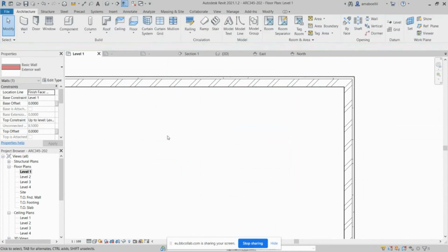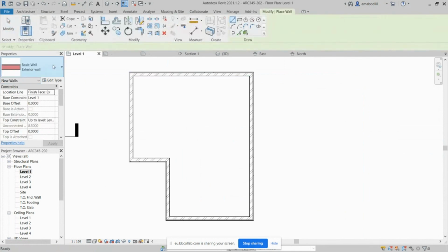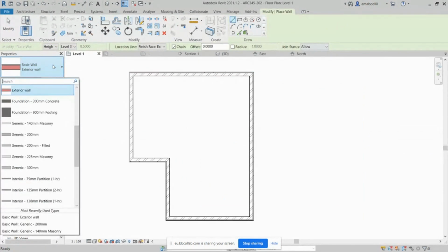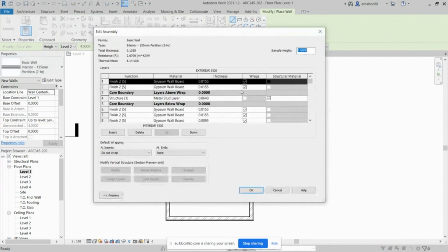So that you have to create your own partition wall and allocate all of the partition to it, differentiating it from the exterior. So if I suppose I will do the same thing, I will go to my wall and I'll pick another kind. I don't want to go to the same exact one, but let's just select this one and then look at the type. It does have metal stud layer, gypsum wall board, and it does have 3 layers of gypsum wall board. I don't know why, but that is built in, and then gypsum wall board from the other side.